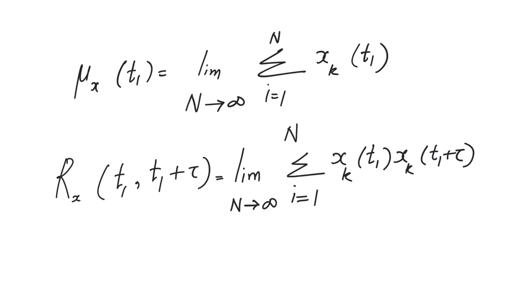Then we went ahead to talk about the relevance of averages for a mathematical treatment of random vibration, and we then defined two ensemble averages. They are called ensemble averages because the average is taken over different samples. As you can see here, the summation goes from one individual time history to the capital Nth individual time history. We looked at the mean defined at a particular time instant t1, and we defined the autocorrelation function also.